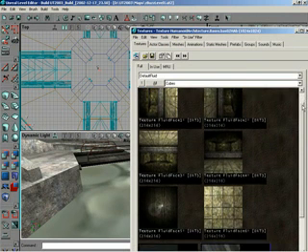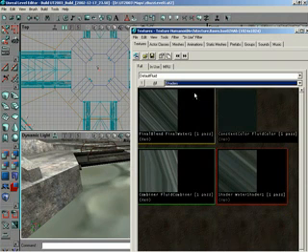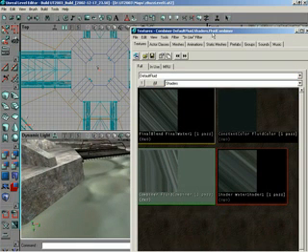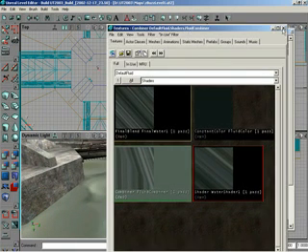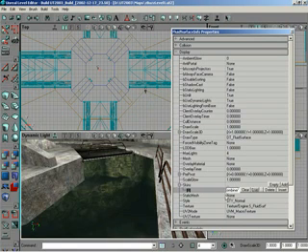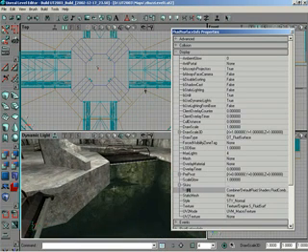We're going to go up under shaders. And fluid combiner, I believe, is the one you used. Yeah, we'll try. That should be that one. Now, with that selected, I can close this out, and it's still selected in that browser, so I can go down where it says skins, and then that 0 that I added, I can click Use, because it'll grab the one selected in the texture browser. And now it's a lot easier to see.